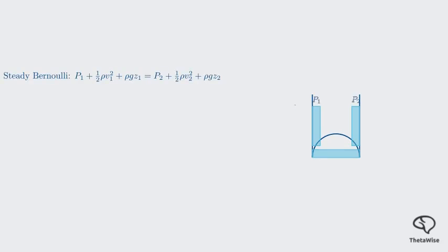Let's look at a simple example that can fool you if you don't consider unsteadiness. Imagine a U-tube filled with water. If we push the water down on one side and release it, what happens? The water oscillates up and down. This is clearly unsteady. The velocity at any point in the tube is constantly changing direction. A common mistake would be to try and apply the steady Bernoulli equation. You might say the pressures at the 2 surfaces are the same, atmospheric, and the velocities at the extremes are 0. Bernoulli's would suggest that the water level should be the same on both sides at the start and end, but we clearly see an oscillation.